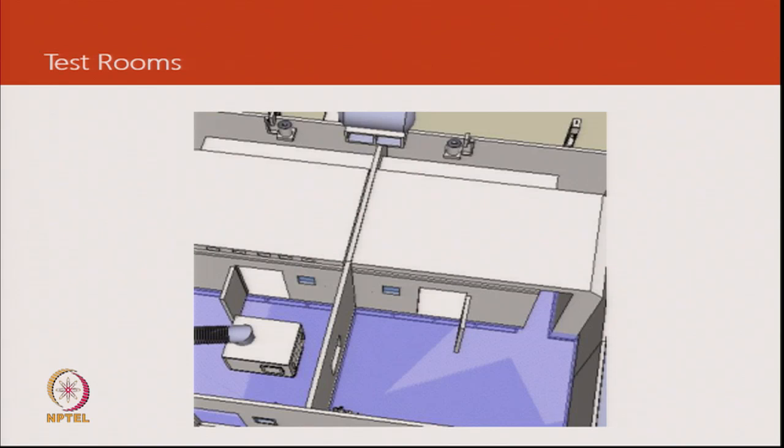We neutralize the pressure drop in the duct by putting in a booster fan. And this requires a certain technical capability to measure the static right at the outlet of the unit, so that when we are testing, we are not disturbing how the unit would operate if there was no duct. So the unit here is going to come into an opening which is in the wall.